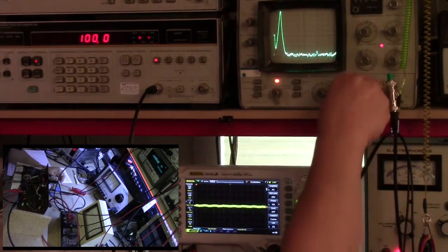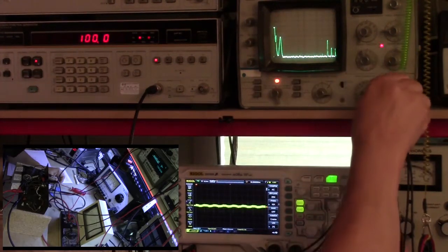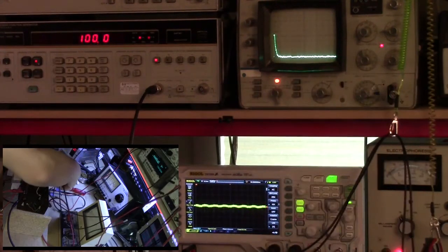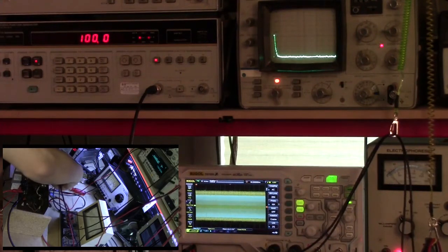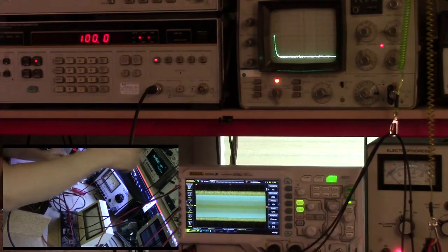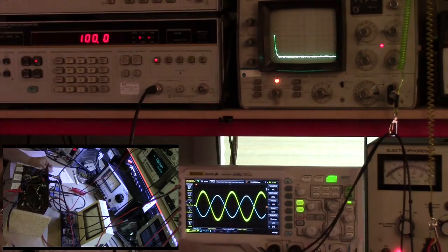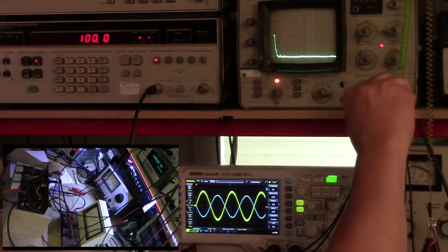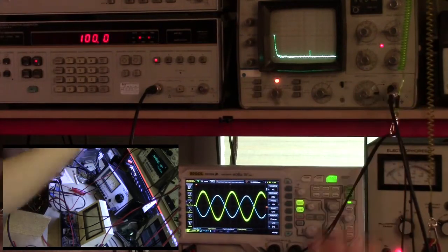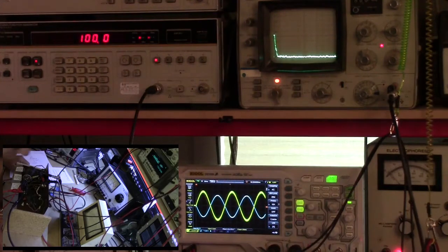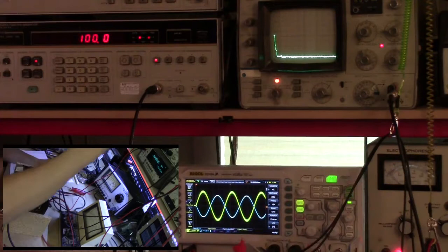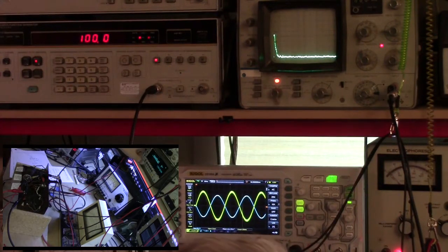Okay, let's go back to our amplifier here. So I'm going to plug this back in to the amplifier, and we'll click that back down, and then we will click this back up here. All right, so now we're back to that. Now, there's a little nuance again with the impedances. This is a 10 megohm input impedance on a scope because I have a 10x probe, and I have that